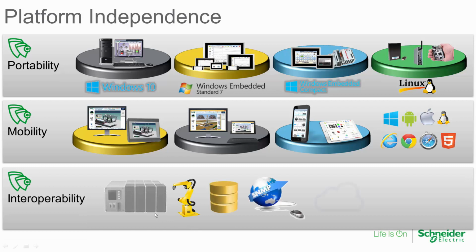And then so much more than what a traditional HMI can do. In addition to communicating with PLCs, there's over 250 drivers built in, and we can communicate to things like robots, temperature controllers, motion control, RFID, barcode readers, databases. You can even configure and interact with networking devices using SNMP protocol, and interact and log to and even deploy on the cloud. You can really interact with or set up the different architectures in so many different ways for interaction there. And I'll bring up MQTT a little bit later.